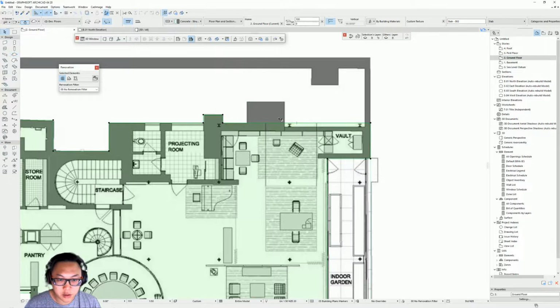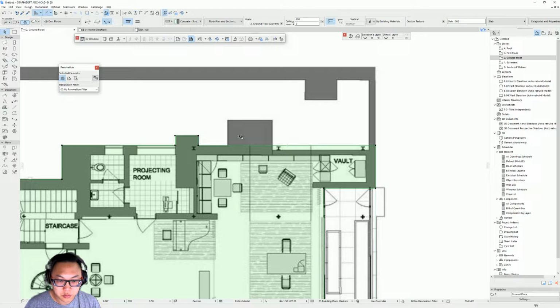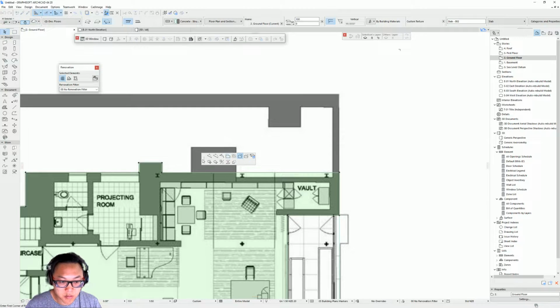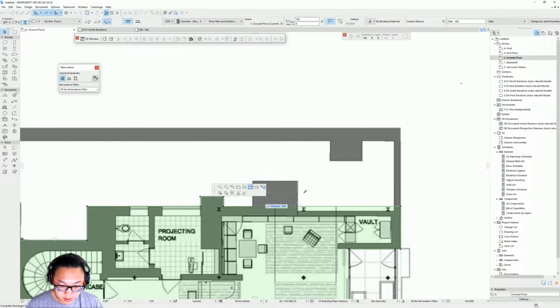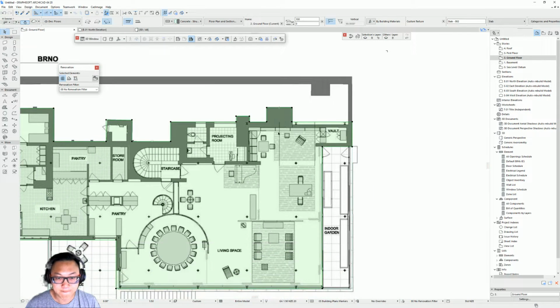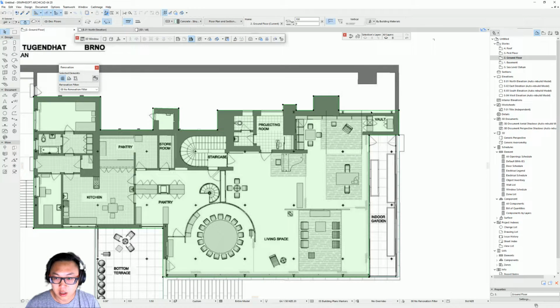And here, let's say you forgot to add something. What you could do is click on the edge, and there's this little palette, add polygon. Add polygon just allows you to add a new part for the slab, and you can either choose the rotated rectangle or the polygonal. I usually use the rotated rectangle. So I start the slab along the edge of the existing slab that I made, and I just pull up. Okay, and this one maybe I'll just pull it down 250.